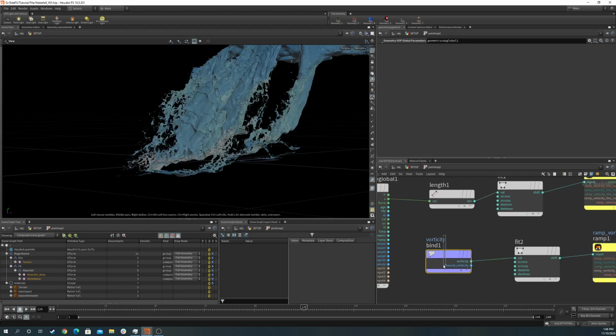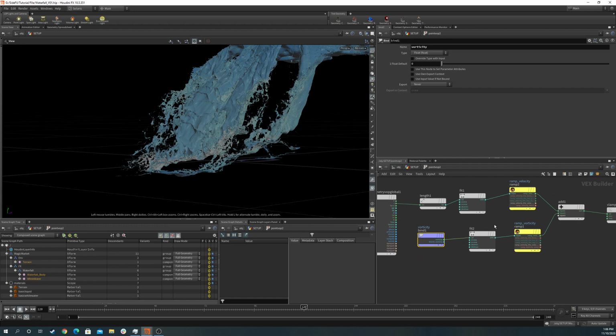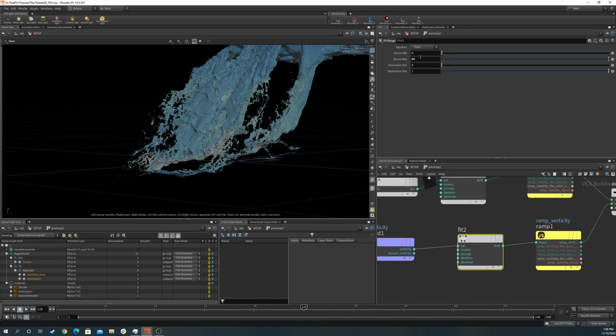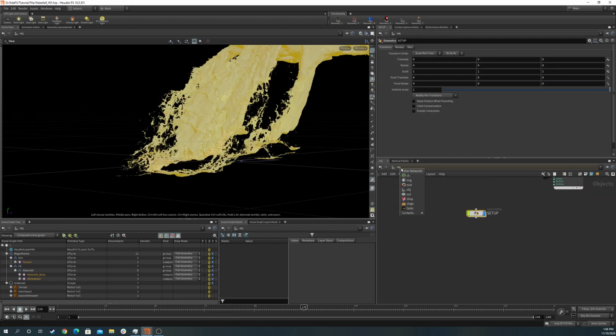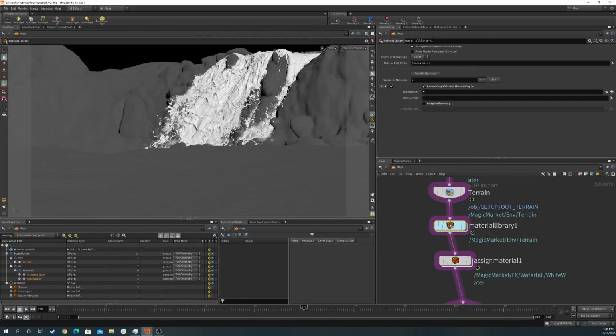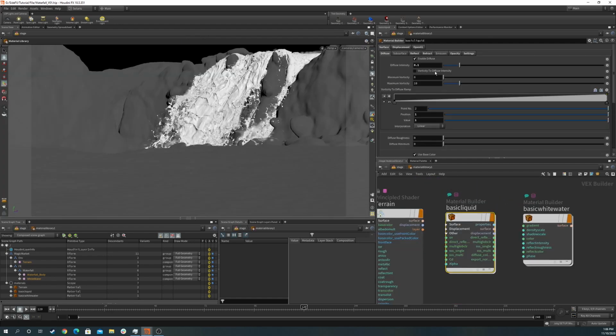We used vorticity as our color ramp to see it. This is our range, 0 to 80, and we can use the same one in the shader. So I'm gonna turn on vorticity to diffuse intensity, and it's from 0 to 80.